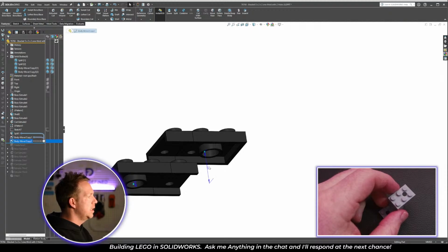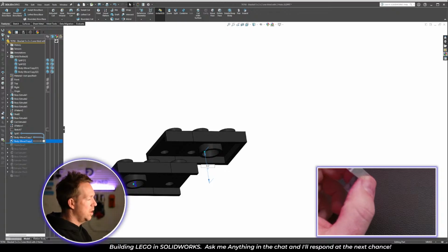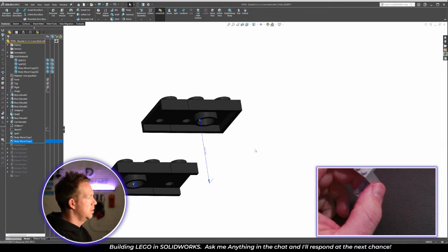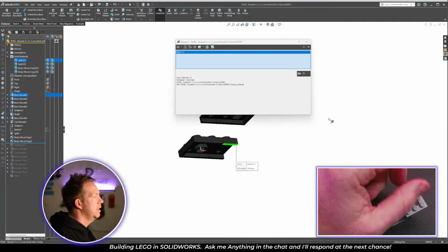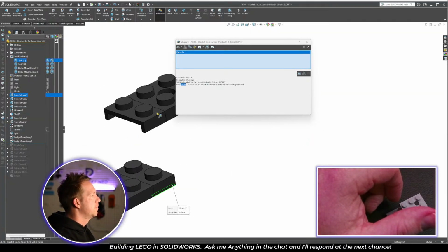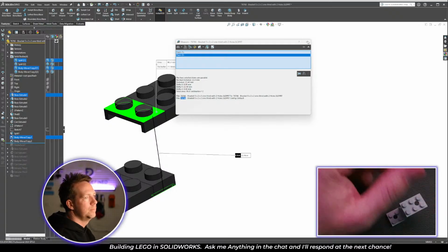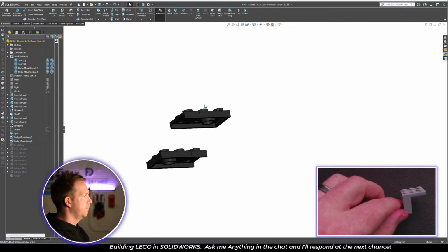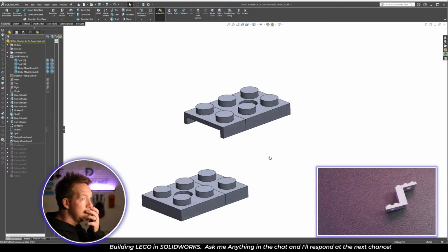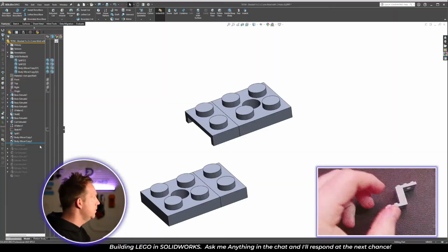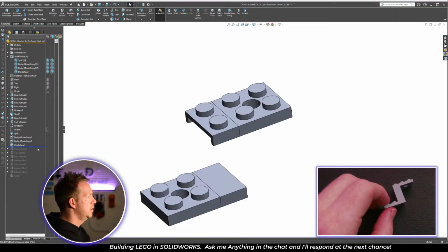So I grab this feature here, that number. Oh, look at that. It's already in there. So just go times 2, 9.6. And so now the overall height should be correct. 22.4. And then we can just roll down the feature tree. Now I'm just going to remove the appearances just so it's a bit easier to see. Roll down the feature tree.